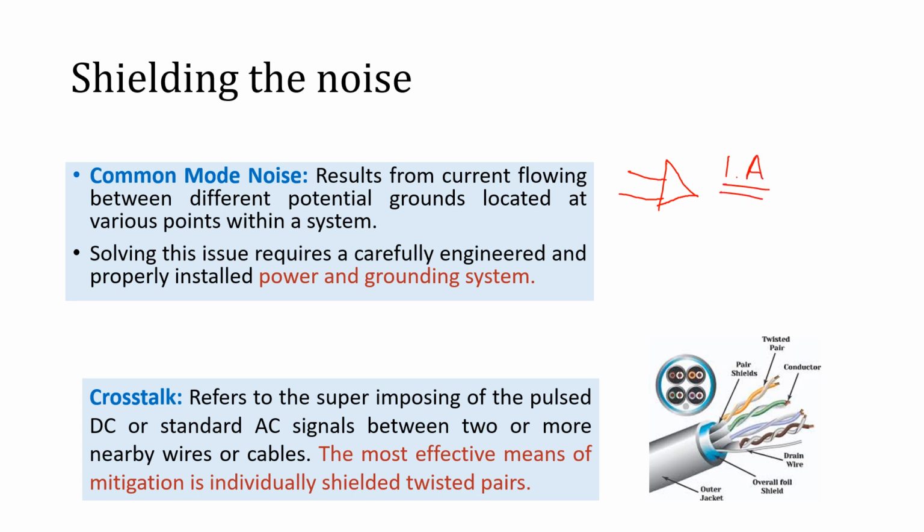We will discuss in further lectures the common mode rejection ratio, and how to remove common mode signal using an instrumentation amplifier. But if I see how grounding can help us, if we use grounding on both sides, for the sensor as well as for the signal conditioning circuit, we can remove the common mode noise. The noise which is common to both the grounds can be eliminated with the common grounding.